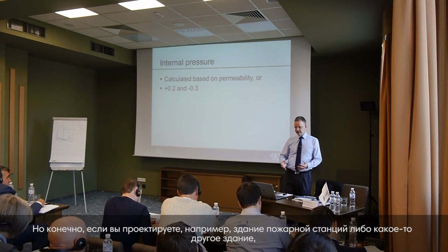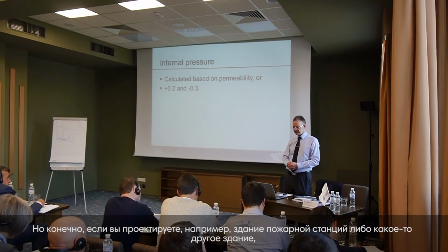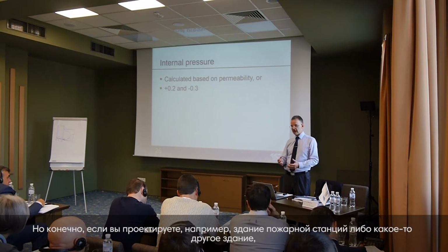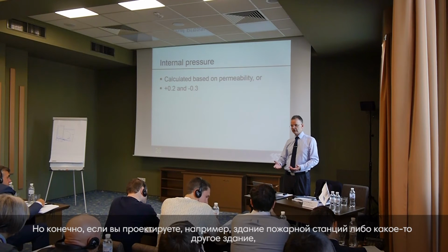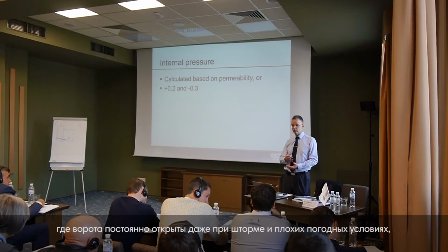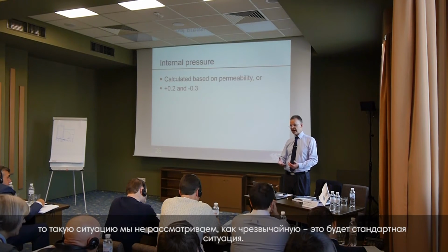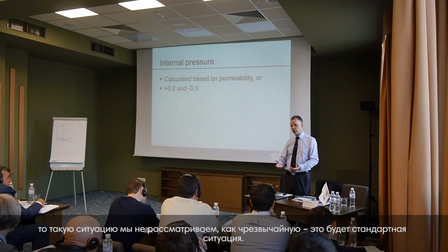Of course, if you are designing a building and it is an ambulance station or a fire station or something where the doors will be open even if there is an extreme storm, then you should not consider it as an accidental situation. You consider it as an ordinary, normal situation.